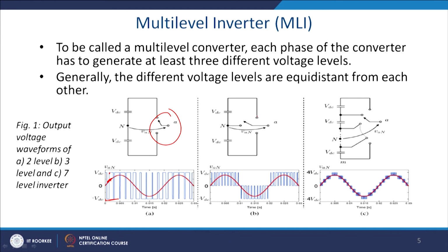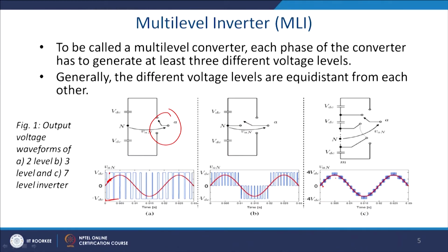It can be connected to VDC, or it can be connected to 0, that is the midpoint of the DC link capacitor voltage, compared to the lower end of the switches. Thus, you can directly see that the stress here is halved, and the instantaneous voltage error has also been halved. With the multilevel inverter, you can see that this error is minimized greatly.